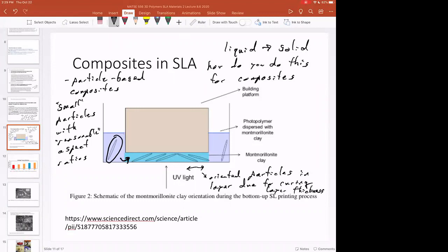And so remember, a polyjet process uses an orifice to create these small drops. And so composites are a lot less prevalent in polyjet because it's just really hard to jet those types of materials. But in SLA, there's a lot of composite and ceramic SLA resins out there right now. And so this is how those sorts of materials are put together.